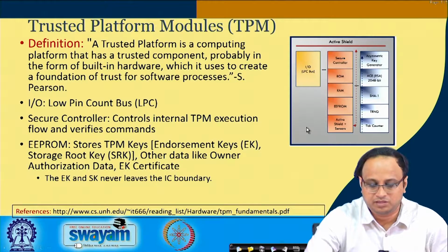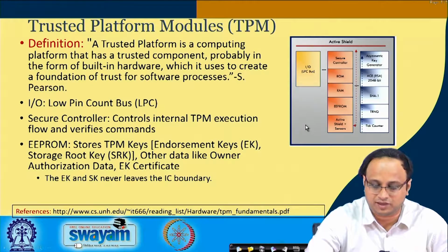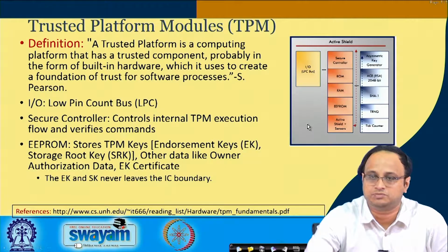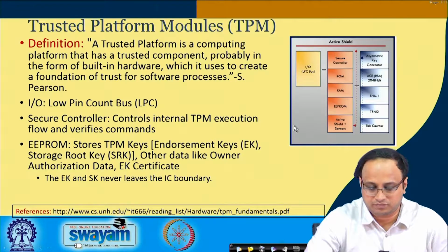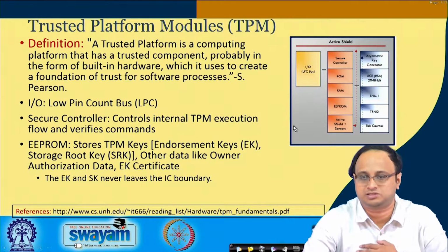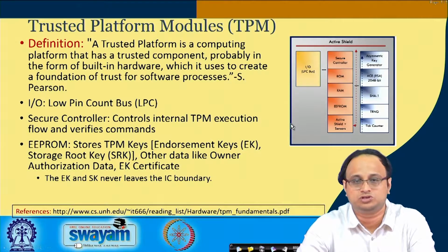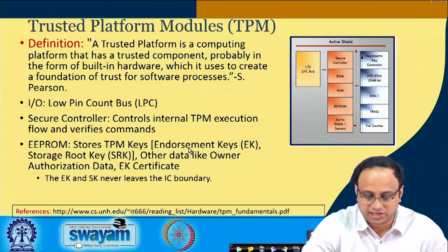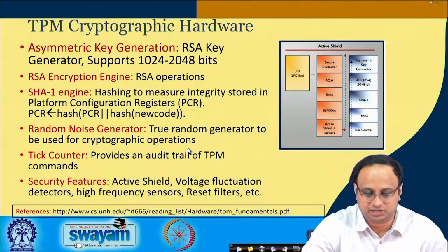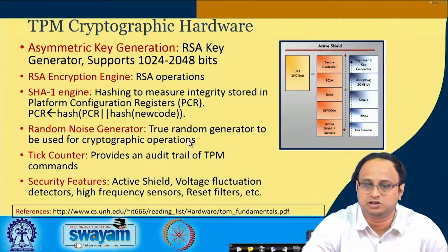Okay. So this is a feature of the TPM chip, and there is some criticism against it also, because even the user who is using the TPM chip is not aware of these keys. This can lead to some privacy allegations and things like that. But at least from a security point of view, this seems to be a very sane solution, where the chip stores the secret key, and this secret key component is never externally revealed. Even the user of the TPM chip is not aware of these keys. So that is the basis of the trust which is built using TPMs.